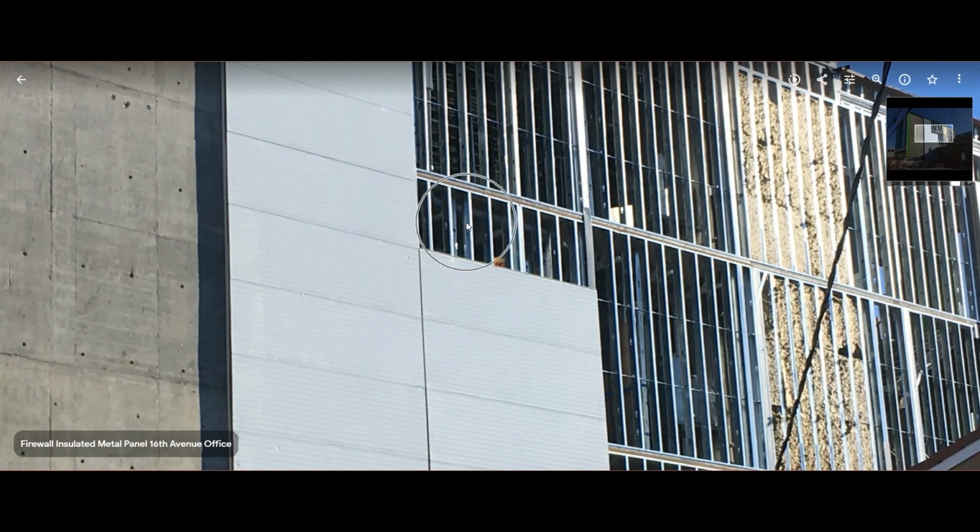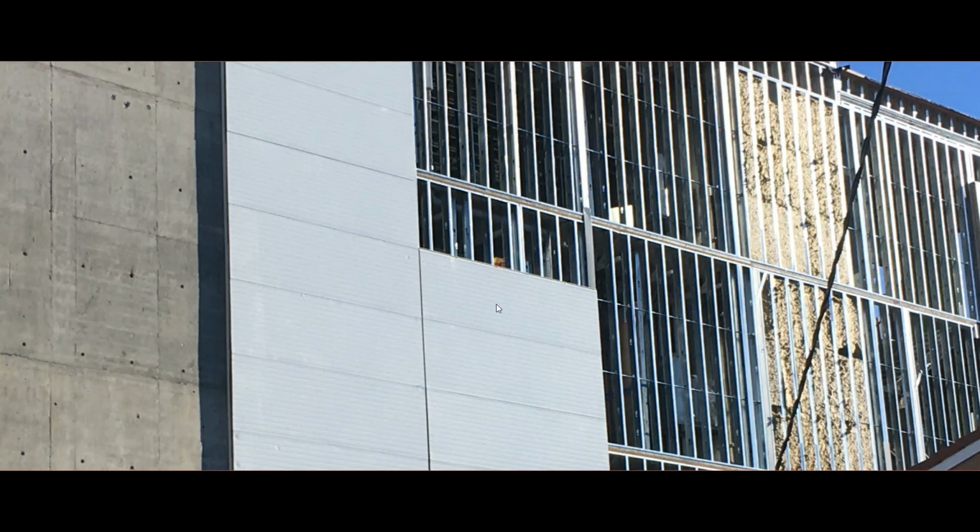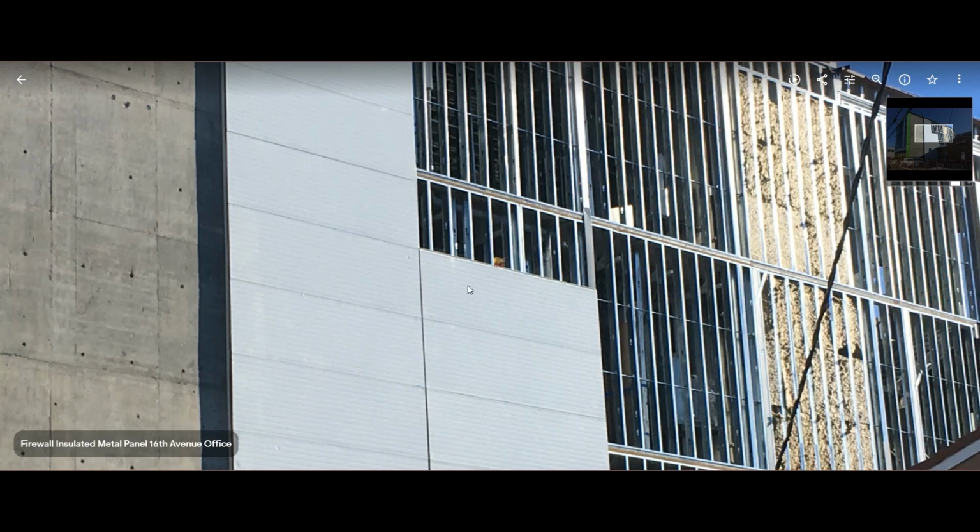a steel stud backup wall, so an uninsulated steel stud backup wall, and then say a couple of layers of gypsum board, I got curious as to what the actual temperature would be of the backside of this panel, again with no insulation in the stud space and no airflow. Really, it would just be an air cavity. I just got curious as to what would the backside of this panel be if it was, say, only 100 millimeters thick. So I'm going to use THERM to figure that out.